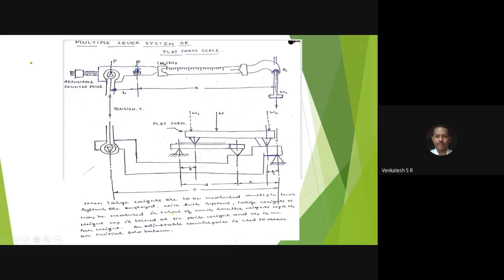Let's go through them one by one. This is the beam. Here you have a movable poise weight, WP, and here you have the graduation. Where this point coincides with a graduation indicates the kg; each graduation represents a kg. Here the dead weights are available that you insert in the hook so that you can measure 25 kg, 50 kg, 100 kg like this.